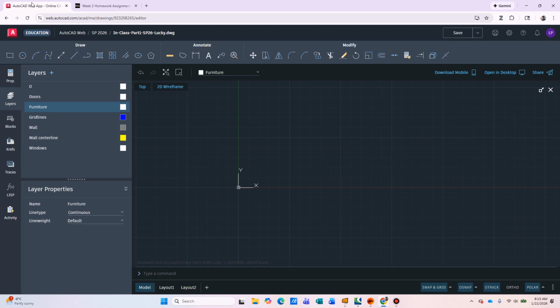All right. So let's start with the wall center line. Just draw any shape. Just make sure that the footprint is 40 by 30. So on the layers, activate the wall center line. Just select the wall center line. And just start drawing using the line tool. And typically, when I'm drawing, I'm going to start from this point. So this is going to be coordinate 0, 0, just to make it easier for us to do the measurement later.